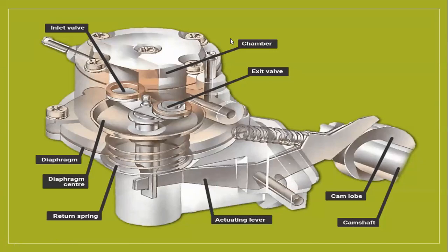Actually, this is the real 3D of the fuel pump. It is not a carburetor. The carburetor's outside is also the same as this. But inside the carburetor you can see the needle valve, throttle valve, choke valve. Actually, this is the diagram of the fuel pump, right? Don't get confused. If I told you it is a carburetor, then everybody would agree. You read this: there are no valves, only the diaphragm is there. But inside the carburetor, the float is there, and the jet is there. The needle valve is there, the spring is there, but not the diaphragm.